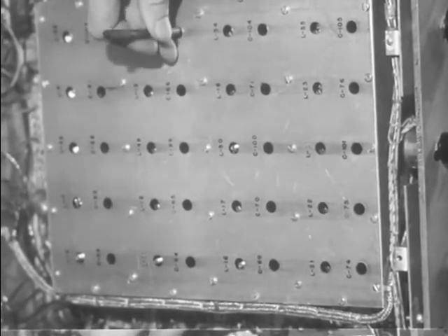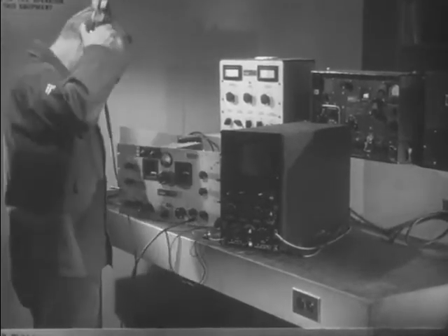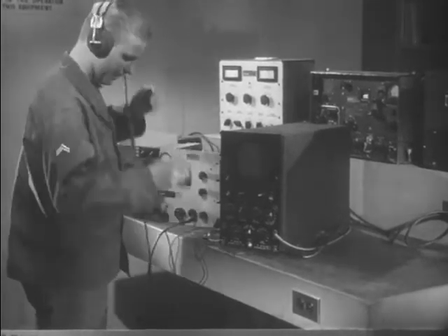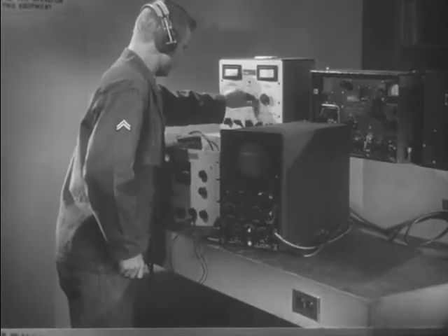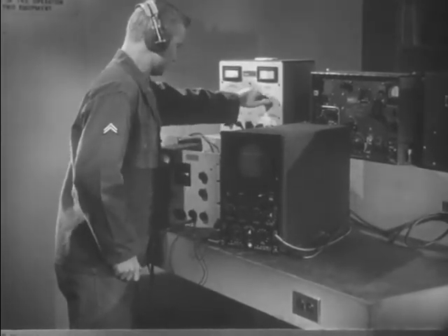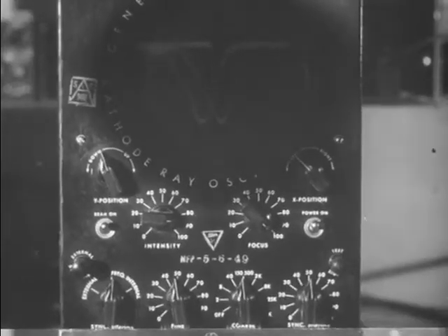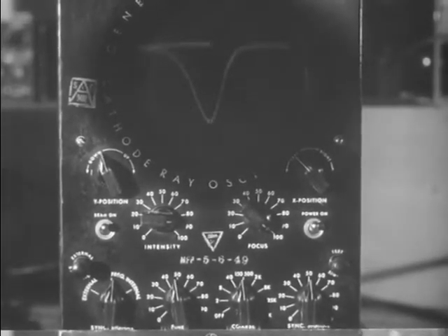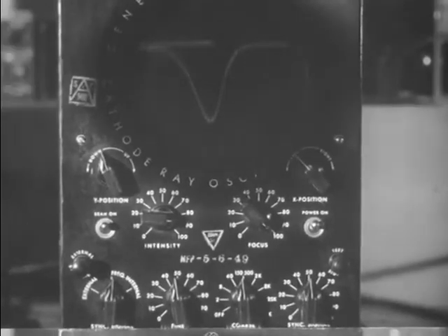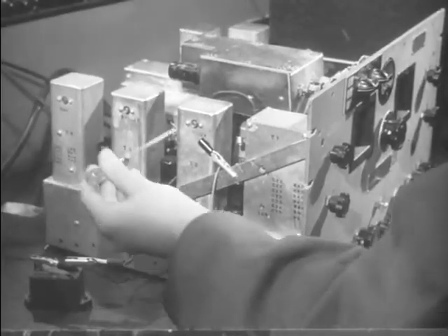For certain types of work, particularly that involving waveforms, the cathode ray oscilloscope is used in place of the output meter. Here, the signal generator frequency is varied at a certain rate over a band that extends 5 kilocycles on either side of the IF frequency. The oscilloscope sweep circuit is synchronized with the signal generator frequency sweep and produces a curve which is a reproduction of the selectivity curve of the amplifier under test. This is very helpful in tuning the IF amplifiers to pass a certain band of frequencies and exclude all others.